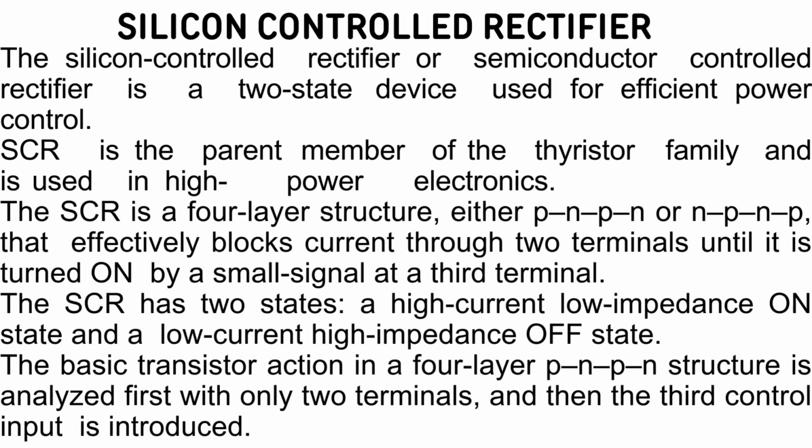SCR is the parent member of the thyristor family and is used in high power electronics. An SCR is a four-layer structure, either PNPN or NPNP, that effectively blocks current through two terminals until it is turned on by a small signal at a third terminal. The SCR has two states: a high current, low impedance on state and a low current, high impedance off state.